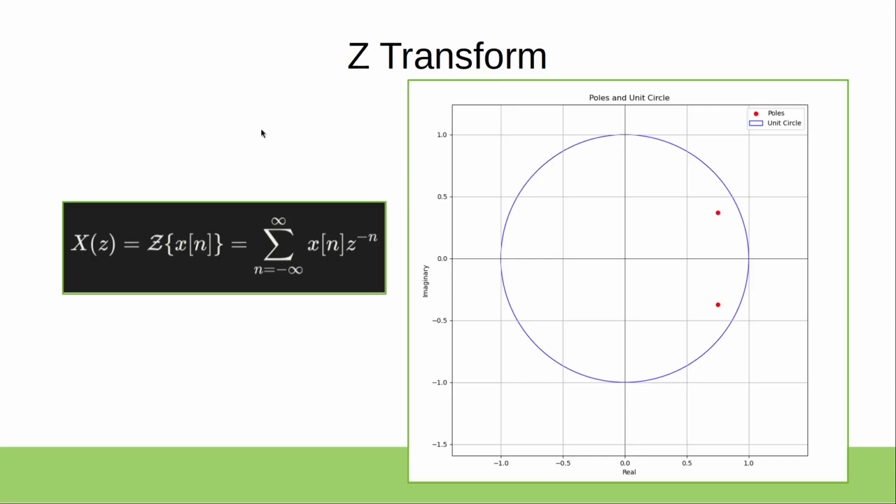The difference between the pole-zero plot and the plot that you see now is that the imaginary axis basically becomes a circle. Any dominant poles outside of it will signify that the system is unstable, and if it's on it, then it's marginally stable, and if it's inside, then it's stable. So now our system is actually stable within this plot.